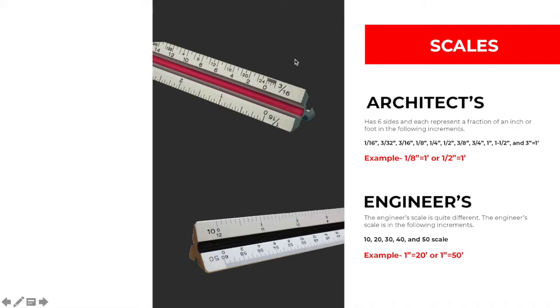You can see to the right of the 0 are portions of a foot, in this case 3 inches, 6 inches, 9 inches, and 12 inches. So if we had a measurement that was, say, 2'6", like the width of a door, that measurement would include the 2 portion here plus 6 inches that is part of that fractional division here to the right of 0.